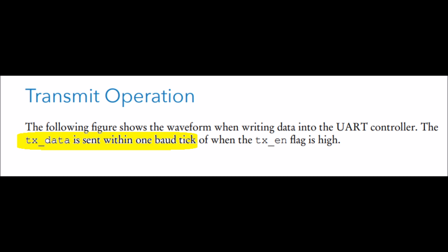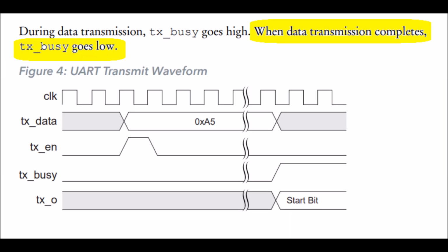One solution would be to use some timing method to measure a pulse of the baud rate. The other option I used was to analyze the bit that indicates whether the transmission is busy, using this diagram. In this diagram, the clock signal should not be confused with the 50 MHz oscillation frequency. It refers to the UART baud rate clock.